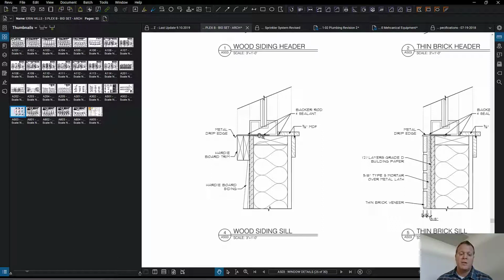So we might have a little bit of coordination to do, but that should be done through submittals with the engineer, and the architect in this case, and show them we've got a different system that the client picked out than what's actually drawn. And so some of these flashing details might have to change, and we might have to follow the manufacturer's literature rather than what's shown in this. And the architect and engineer would be fine with that kind of stuff. That's what you're supposed to do.